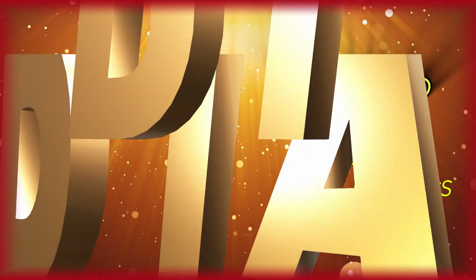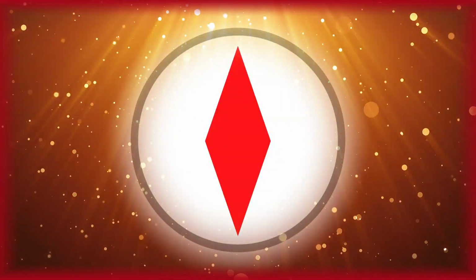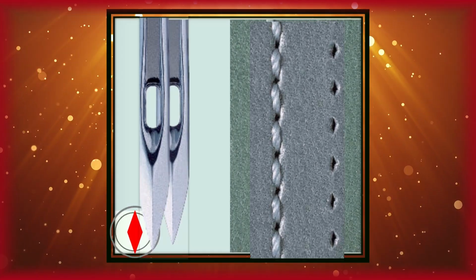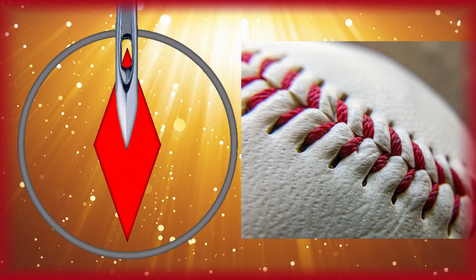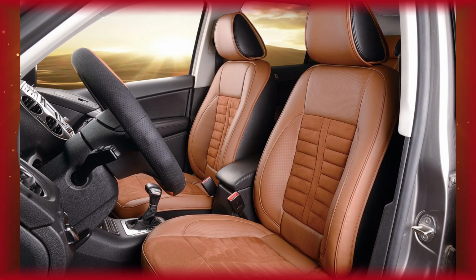This is leather's worst nightmare. It cuts clean holes. DI or DIA point needles are characterized by a diamond-shaped point that creates a quadruple edge hole in leather, resulting in very straight stitches. The sewn thread is slightly raised, and the stitch holes are clearly visible. Diamond point needles are widely used for crafting leather goods such as belts, bags, footwear, upholstery, suitcases, and other similar products.